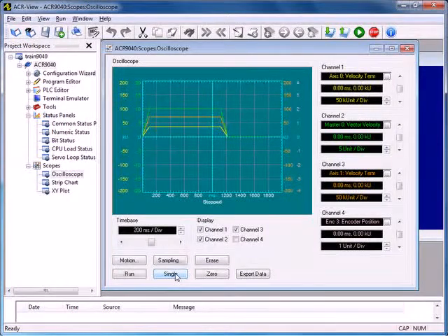So you can see the trajectory velocity is still 10, but the x-axis is now lower since it's only moving 5 revolutions. My y-axis is my channel 3 that has to move twice as far, so the velocity comes out to be about twice as much, but it reaches the end position at the same time.